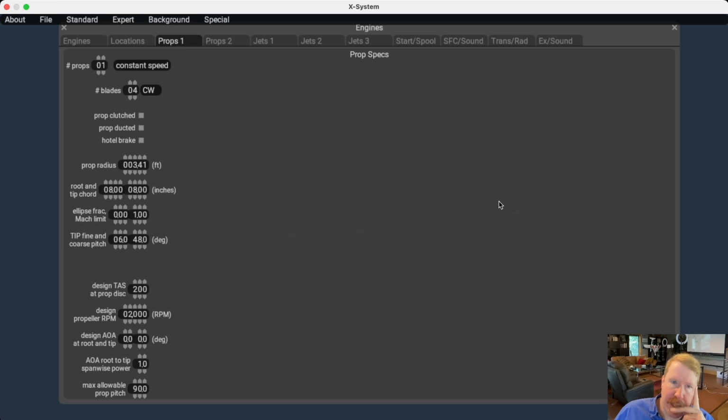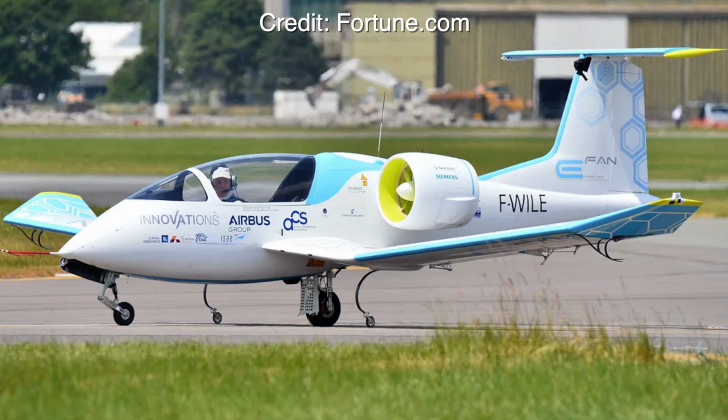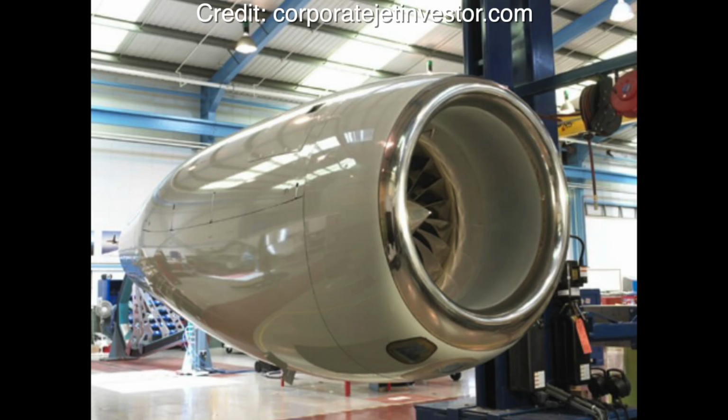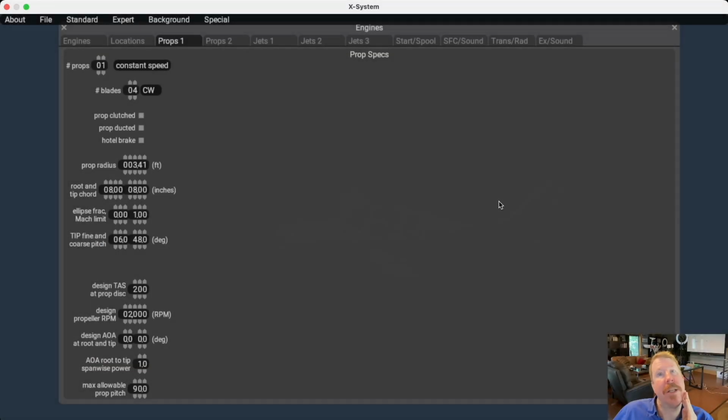And what these ducts do for propellers is they keep the tip losses minimized, because the propeller is now spinning inside a duct, you see. And the tip losses don't really happen so much because the air can't make it around the prop because the duct is there stopping that from happening. And so a duct is good for super, super low speed because it blocks those tip losses. That's not to be confused with an engine nacelle on a jet engine, which slows the air down and actually makes the compressor more efficient at high speed, because the inlet does some of the compression first before the compressor has to.